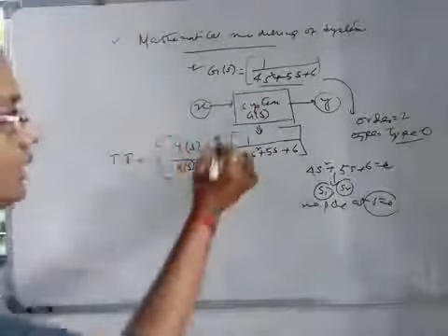The overall voltage of the loop is equal to zero. So that is the KVL, and we get vi(t) equal to iR plus L di/dt.